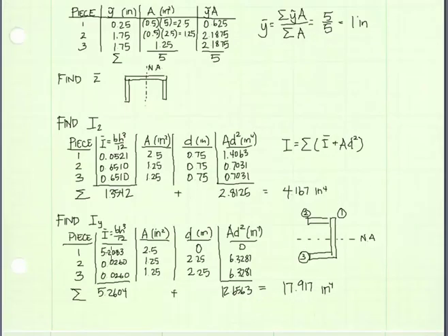Okay, to find the moment of inertia about the y-axis, we can essentially take our cross-section and flip it. So now the y-axis is showing as horizontal, and piece 1 is still the same piece, but the values for b and h are changing relative to the moment of inertia values for that piece about the z-axis. And the areas for pieces 1, 2, and 3 stay the same.